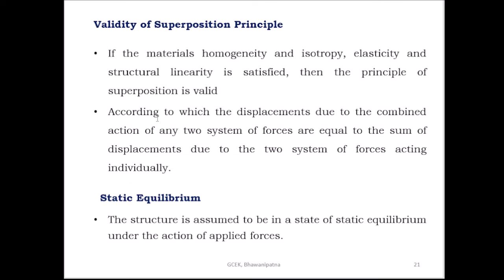So according to the principle of superposition, the displacement due to the combined action of any two systems of forces is equal to the sum of displacements due to the two systems of forces acting individually. So this is the assumption, and this is valid for the analysis of the skeletal structures.